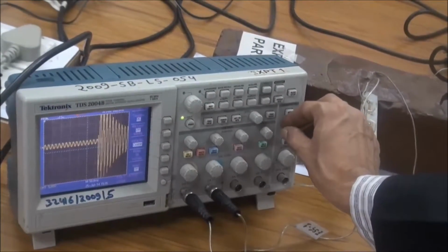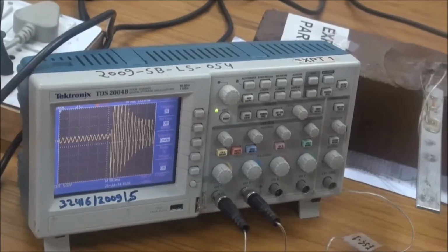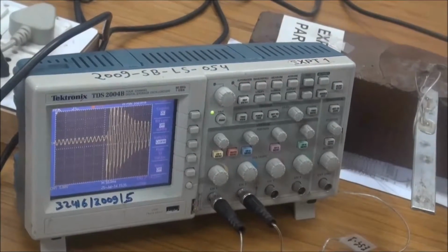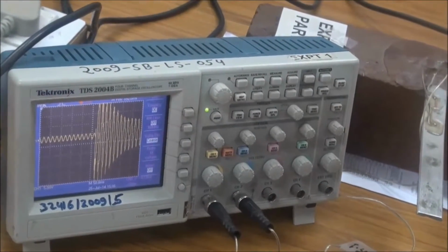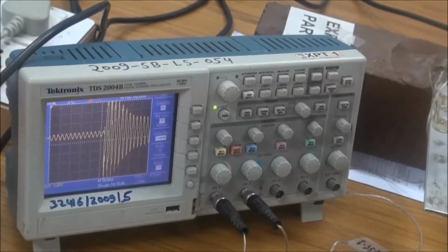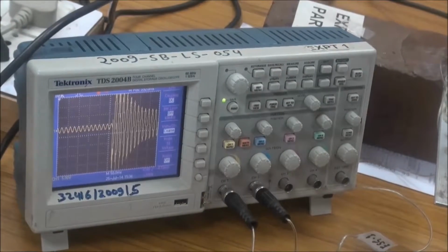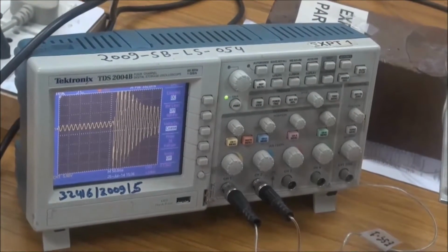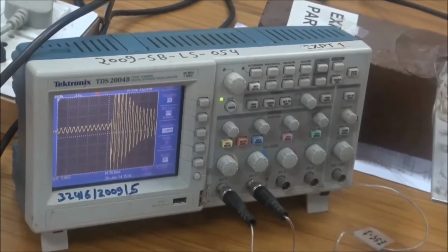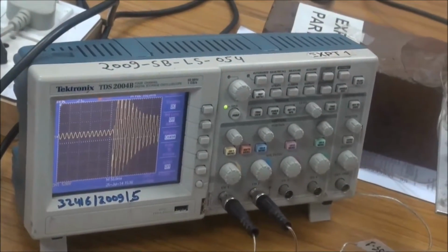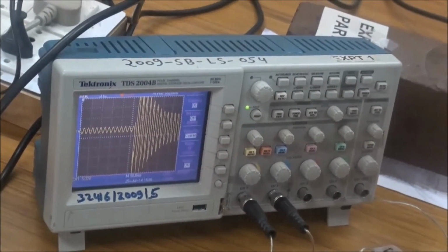Now if you see here the signal, this is like an oscillating signal. So here you can see the voltage is changing from positive to negative and continuously going in this cycle. So essentially the vibrations of the structure are very well captured by the piezo patch. So now the structure becomes smart because it is sending the state of the structure, which the user can make use of. Now after this, we will take you to one experiment involving energy harvesting.